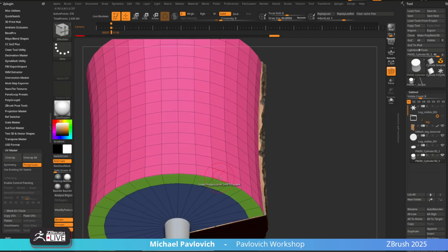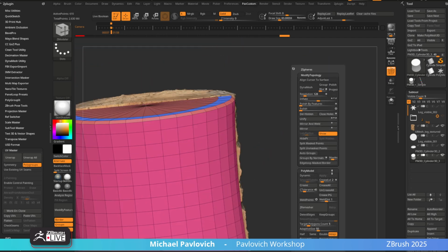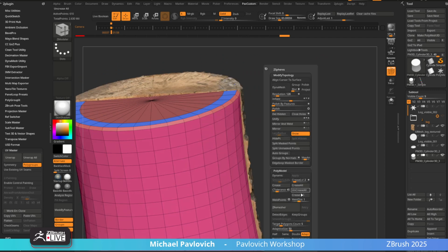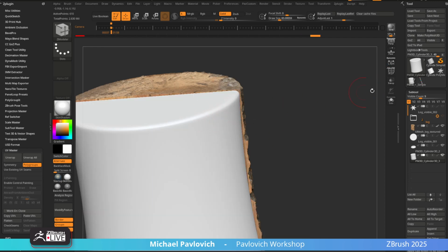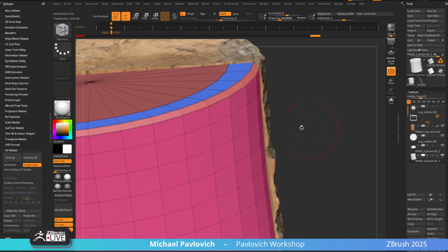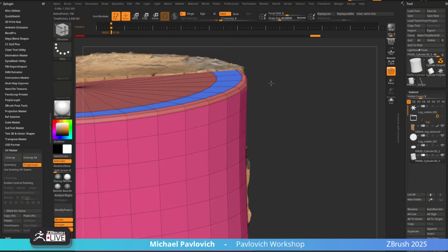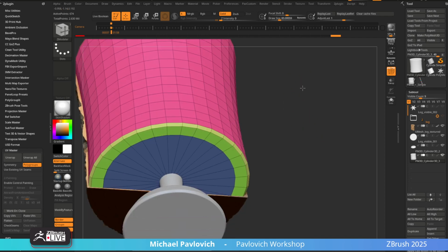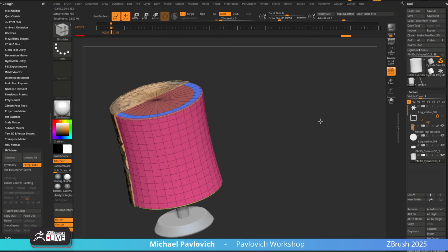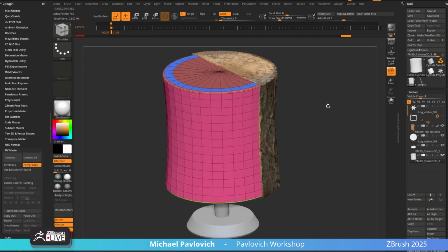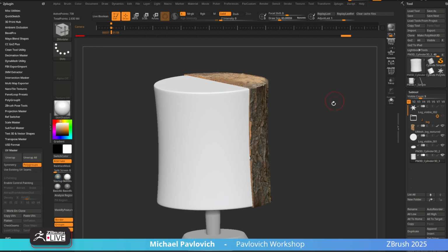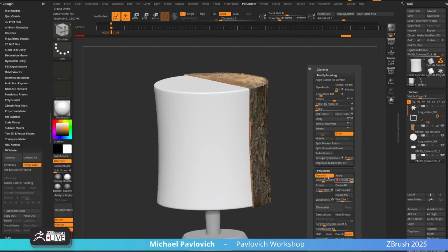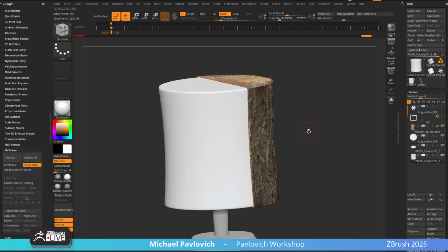Now, if you wanted to have even more control, or if you're doing nanite modeling, where if I do a crease PG and dynamic and crease level of 1, maybe I'll get a softer falloff. But you can also go in here and say insert multiple edge loops, interactive elevation. You can just pull and give yourself more resolution this way. Let's say uncrease all. That way you don't use any creasing. You just build in the geometry you need to soften that out. I don't know, that might work fine. So we'll just hit D for dynamic. We're not going to use any crease level or anything like that. Just uncrease all. And there's our resin tank.